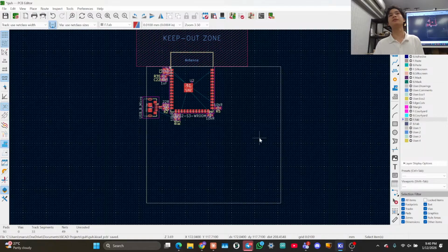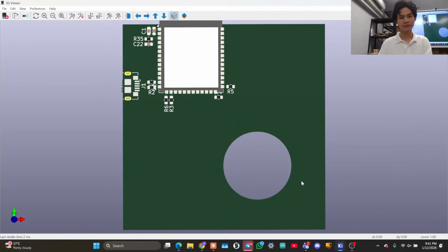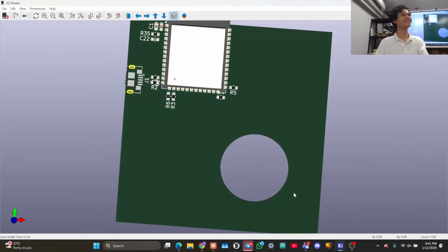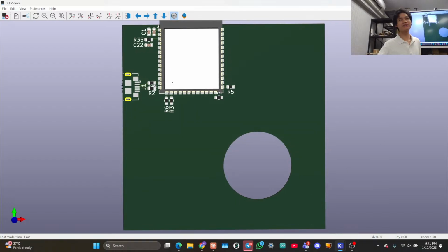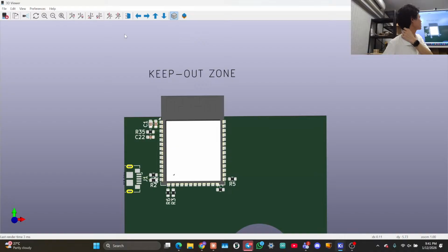Penny, how do I put a hole in the board? No, not mounting hole, like a slot or something. So I just do this. Is that it? That's not that because that's broken, but this is fine, is it? Like slots. Oh, it was that easy. Oh, I was just in the wrong layer. I was in the fabrication layer. That's why it didn't work. Yeah. Okay. So I guess you can just put a huge hole here if you wanted to.